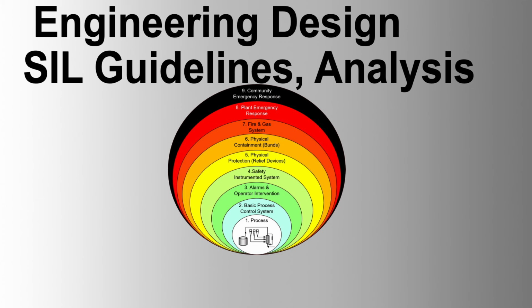System modeling. System modeling of any fault-tolerant E/E/PES architecture can be done using simplified equations, fault tree analysis, Markov models, or other techniques using the failure rate categories described above. Accurate and detailed failure modes, effects and diagnostic analysis, FMEDA, is essential for this classification.